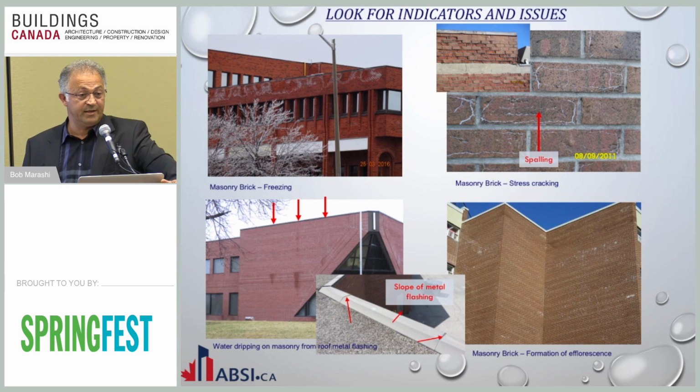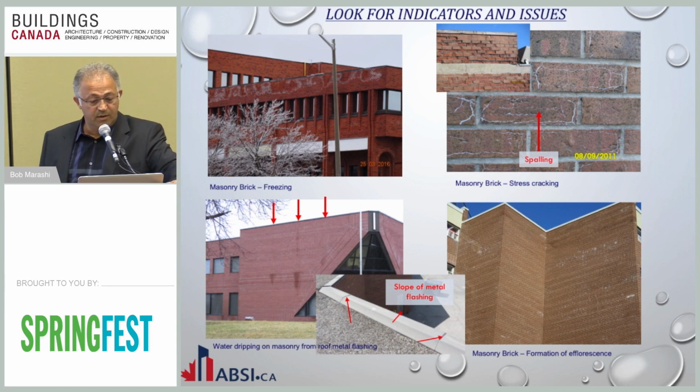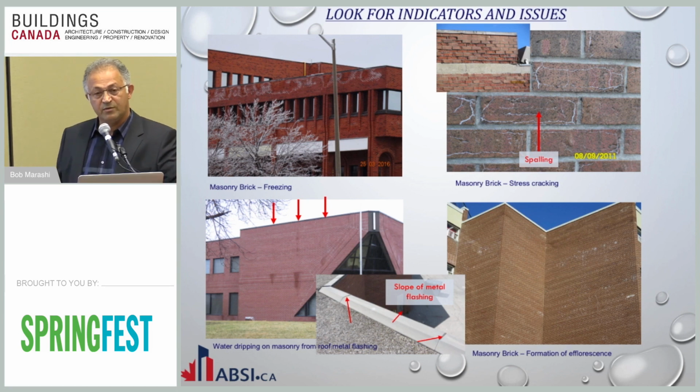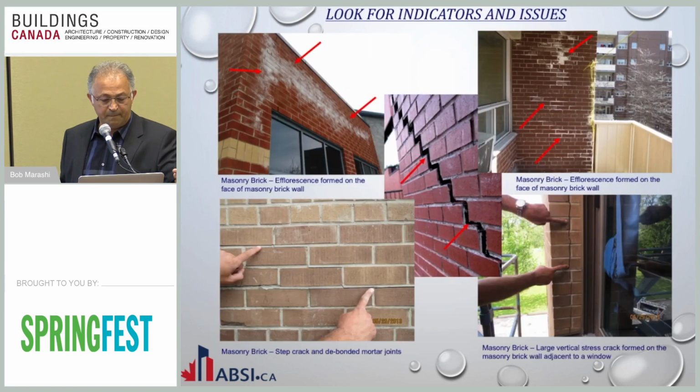It's getting in there and drying out on your surface, depositing salt on the surface of the wall. It's an indicator for you to actually do something about it, not to just go clean it and walk away from it. You actually do need to find the source of moisture entry and do something about it to save your building.